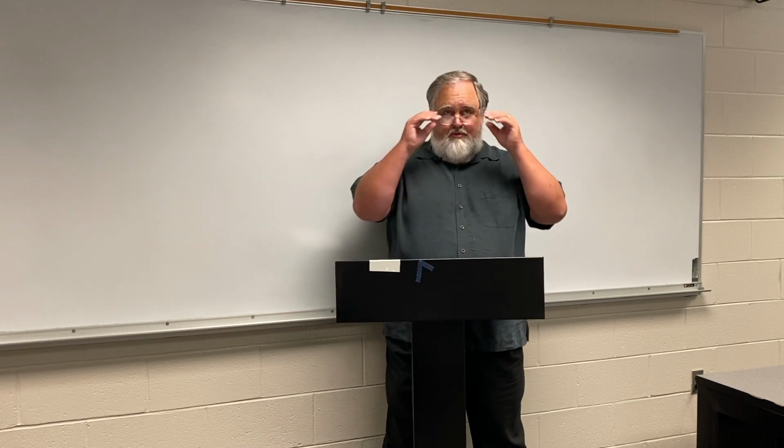Yes? A span is the distance from one support element to another support element. So we'll talk about the platforms here in a minute. Typically in a 2x4, 4x8 platform, 2x4 is the material, 4x8 is the size of it. Having a support every 4 feet is fine. Now, if you're gonna have 20 people on there jumping up and down, you might put a support every 2 feet, which is going to double the strength of it. Yes? If you know that that's going to be mistreated in that way, that's one way that's very, very cheap, very easy. Just construct it twice as strong.